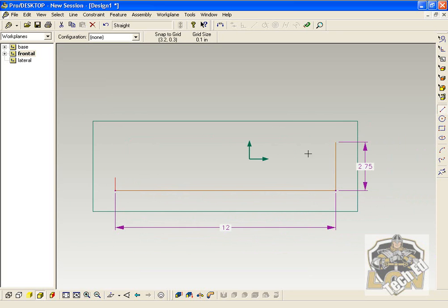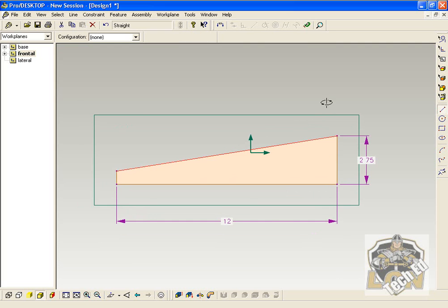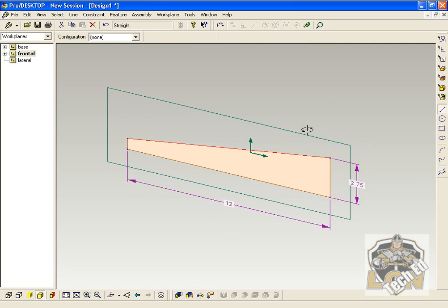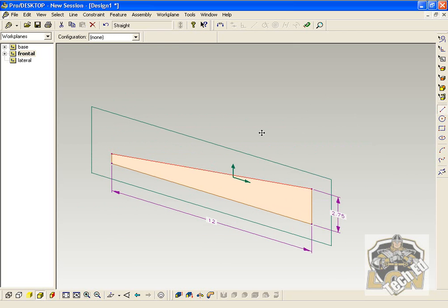And then I can just play connect the dots from this endpoint to this endpoint, and we have a CO2 car profile. The last step is extruding this. So we've dealt in 2 dimensions, kind of like X, Y, or height and length. I'm going to tilt it on an angle a little bit just by holding the middle mouse button, and I'm going to slide it back.